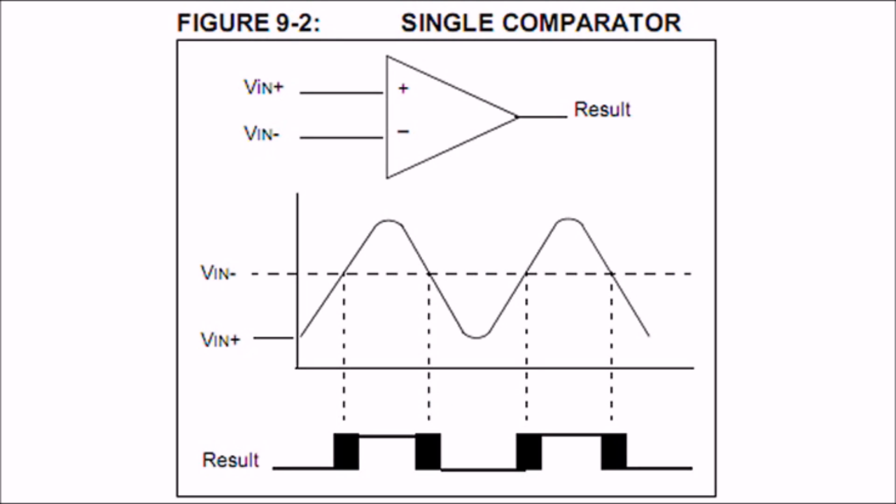What we're looking at here was taken directly off of a specification sheet for a Microchip PIC 16F628. Many microcontrollers, including the heart of the Arduino, have built-in comparator circuits that you can access by setting the appropriate bits in the microcontroller. In the case of the PIC 16F628, it has 2 of them that have a number of differing configurations that enable you to do all kinds of incredible stuff.